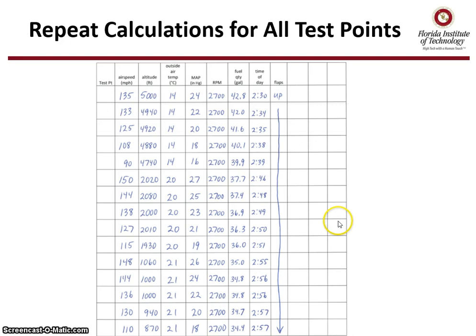We'll then want to repeat all those calculations for every point that we flew on our level flight performance lab, knowing that you're going to have to go to that engine chart with the temperature, manifold pressure, and RPM and calculate a brake horsepower for the test day.